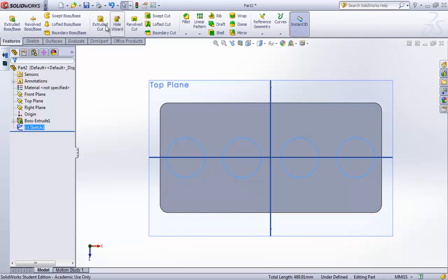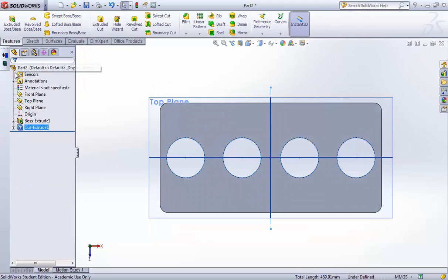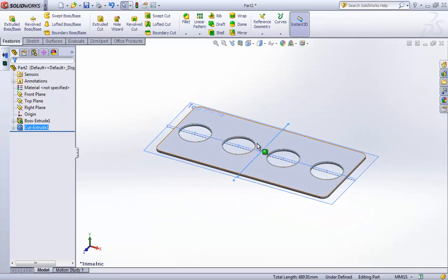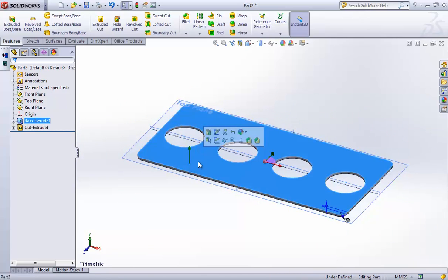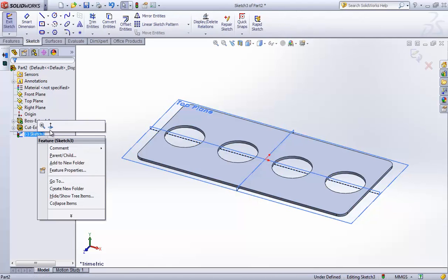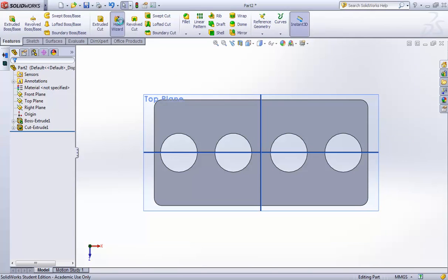Exit the sketch, extrude cut, and stamp the circles out of the blank. So we have an arrangement like this. If I was to do it properly, I would make sure that these are correctly dimensioned. So next up is getting the holes all around, and as I said, I'm only freestyling this. I don't think I want to do that. I want to use hole wizard.